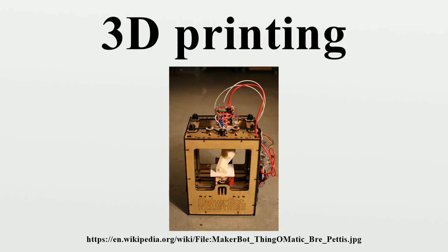The build plate then moves down in small increments and the liquid polymer is again exposed to light. The process repeats until the model has been built. The liquid polymer is then drained from the vat, leaving the solid model. The EnvisionTEC Factory is an example of a DLP rapid prototyping system.